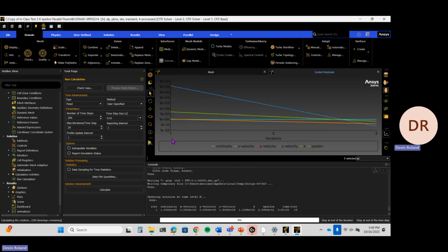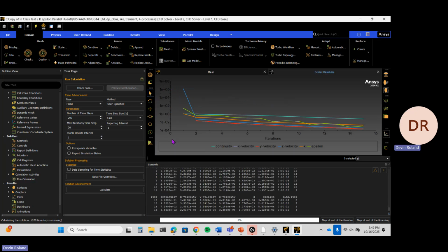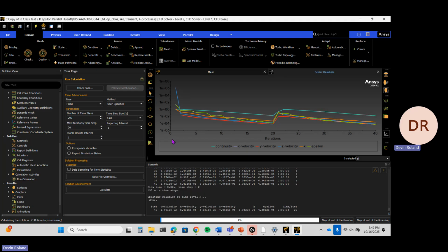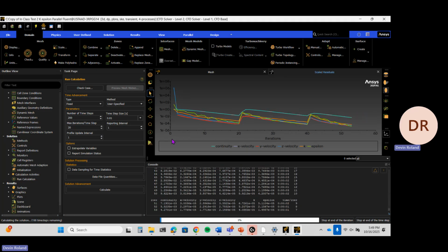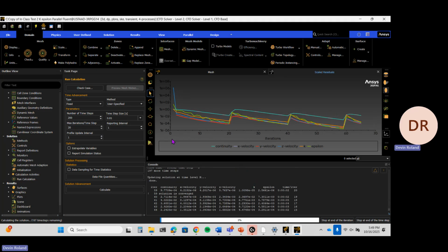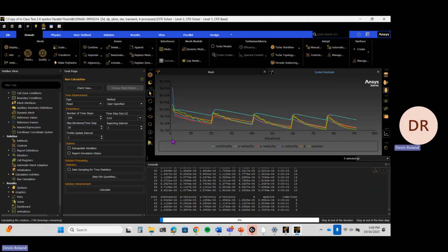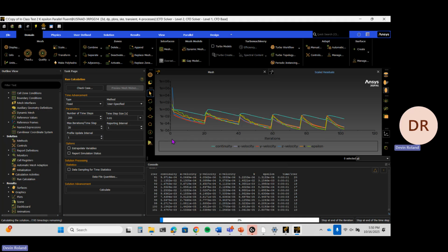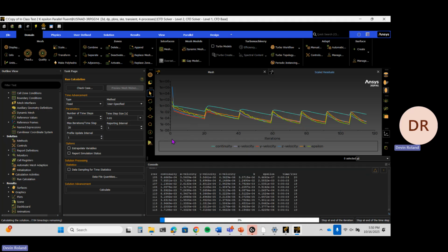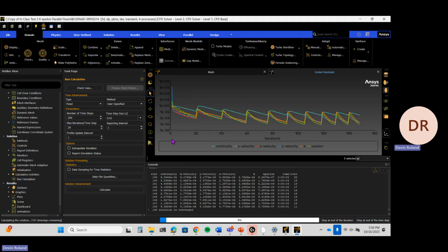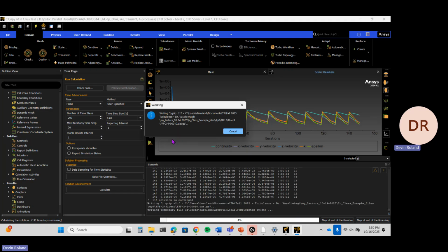So what I'm thinking is maybe let this run. Then we can maybe print out contours of velocity and TKE and anything else you want to look at. And then we could do an LES case and then print out TKE and contours of velocity. And then you can observe how the models have different motion behind the trailer.